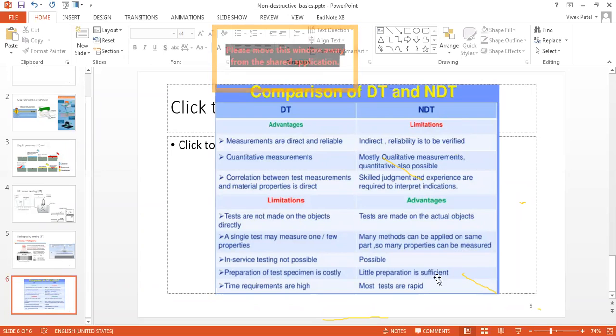You want to take some decision for quality control. When you are manufacturing something, your production line is going on, and you want to make sure, let us say you are producing 1,000 pieces every day. In that case, NDT can be used to monitor the quality of the component. And destructive testing is more about developing the material at the initial stage, right? That's why we go for tensile testing, hardness testing, so we know the properties of the material. Non-destructive testing cannot give an idea about the properties. Here NDT will give you more information on the defects instead of the properties.